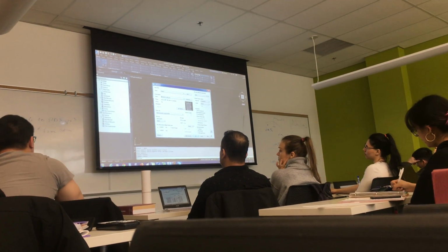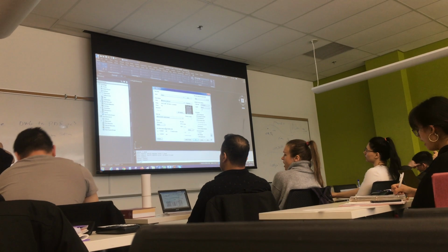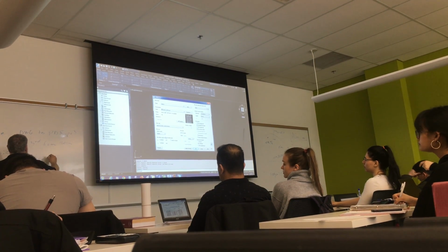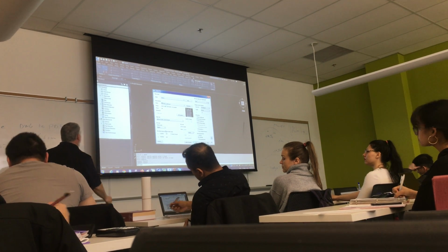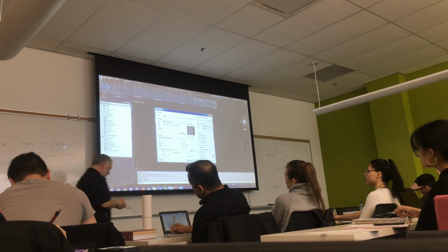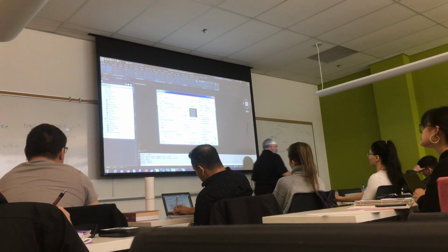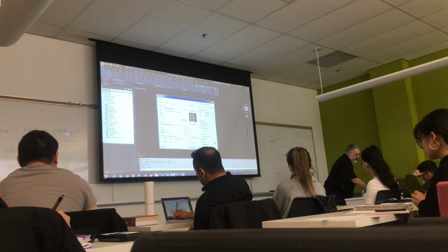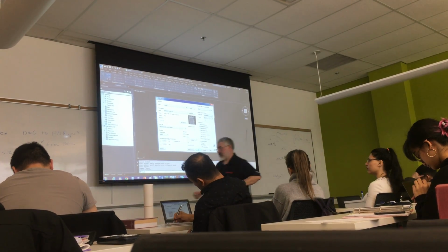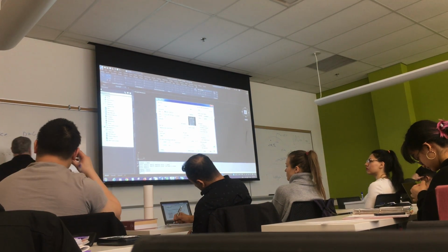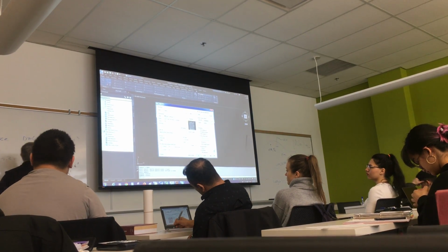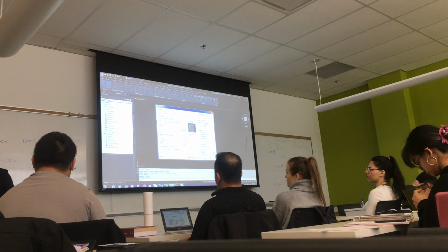That's the device. The next thing you want to look at is paper size. Use a 24-inch by 36-inch, which is typically a D size page. D size. 24 by 36-inch D size architectural size page.